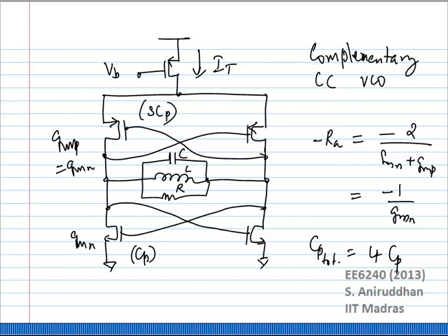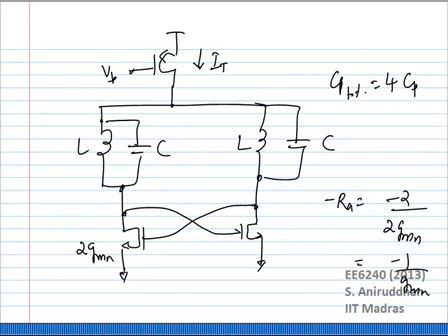But I gave the example of an NMOS cross-coupled pair where you actually just make it twice the size. You will get negative resistance that will become half, more dominant, right? So that is not necessarily a reason, with the exact same tuning range hit. Okay. So that is not the reason why anybody would move to this particular circuit topology.